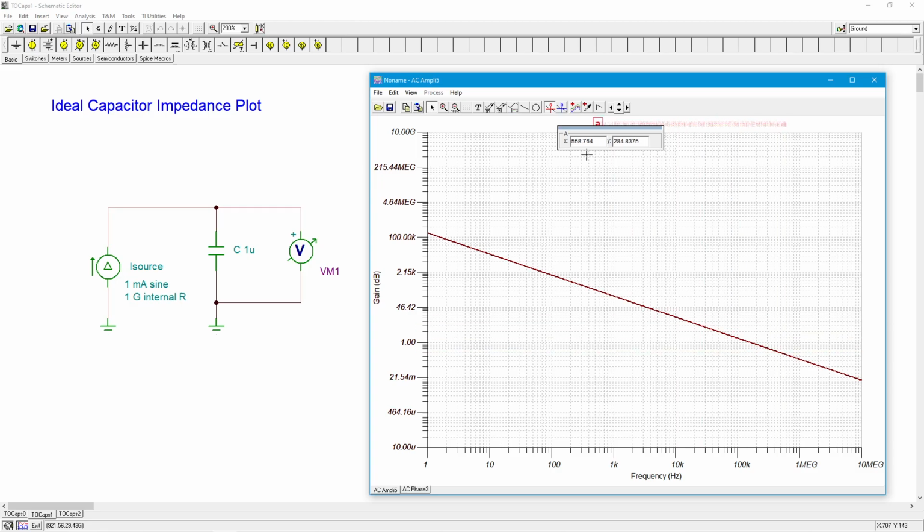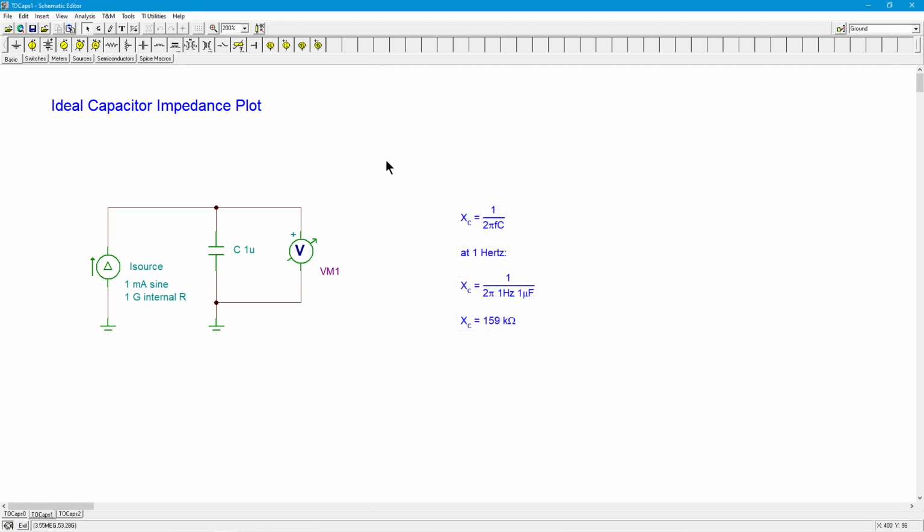All right, nice straight line. When you plot this on a log graph, you get this nice straight line. That's your idealized capacitor. Goes on forever. Pretty soon at these high frequencies, you can see we're getting milliohms, micro ohms. We're getting really small values. Okay. That's not realistic. Sorry. Be nice, but it's not realistic.